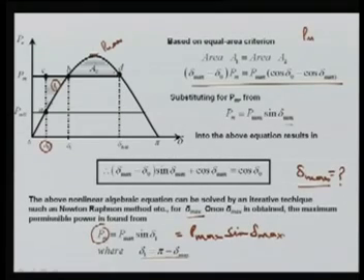However, area A2 is the decelerating area, because your PE is more, meaning the electrical power that you are taking from the system is more than the power you are feeding to the turbine. So this is decelerating. Accelerating energy must be equal to decelerating energy. Then the PM can be determined.